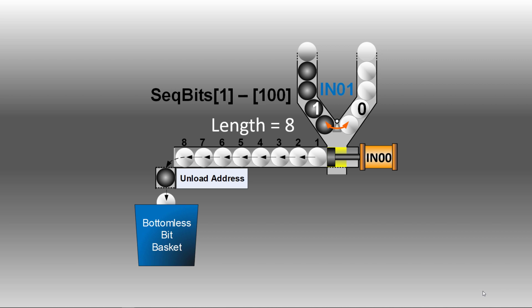So we'll designate 96 of those, and each one represents 1 inch on the conveyor. Now, you could start at 1 and unload when it reaches, in other words, use a length of 96. And where that 96 starts depends on the offset.